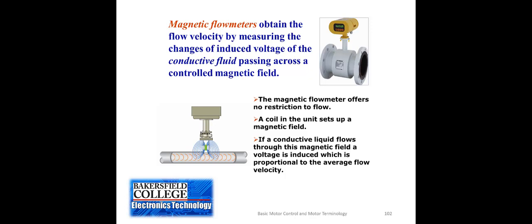That creates a little bit of voltage in that liquid, and sensors measure that voltage. So as the flow rate changes, then the amount of voltage that is sensed will change.